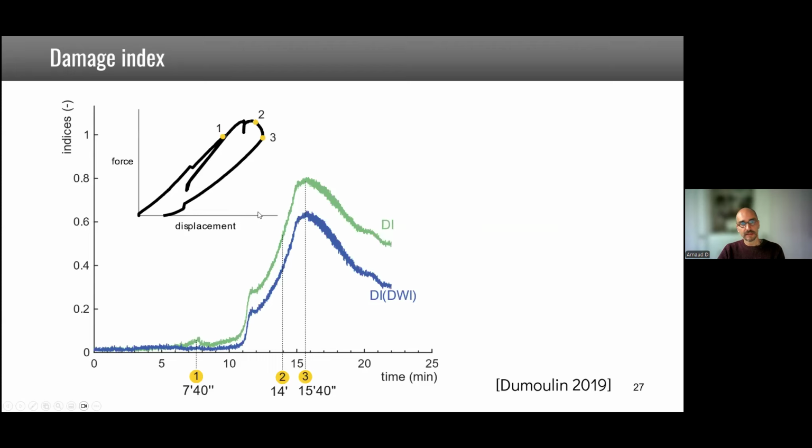Bottom line: if we do the time stretching on the early wave, we get the blue curve. Whereas if we don't do the time stretching, we have the green curve, which reacts here around 0.1 before there is damage, and even a bit before. So time stretching is efficient to remove the acoustoelastic effect, providing you do it on the early wave and pay some attention to these things.